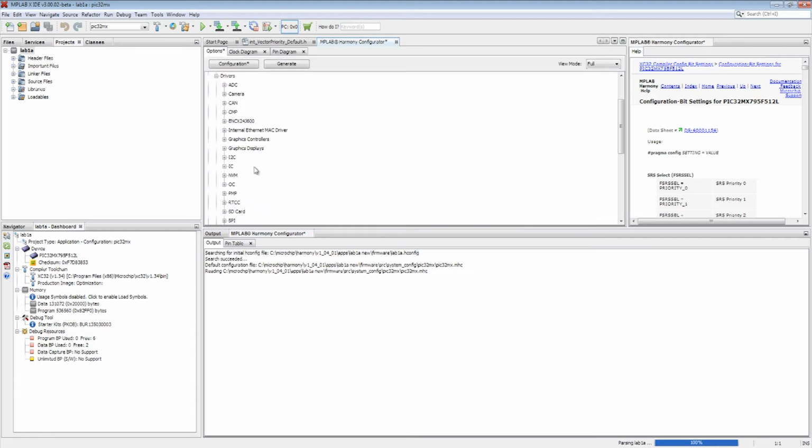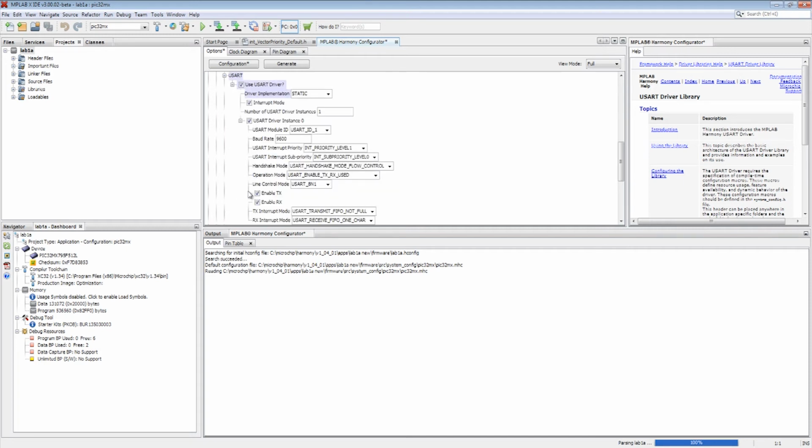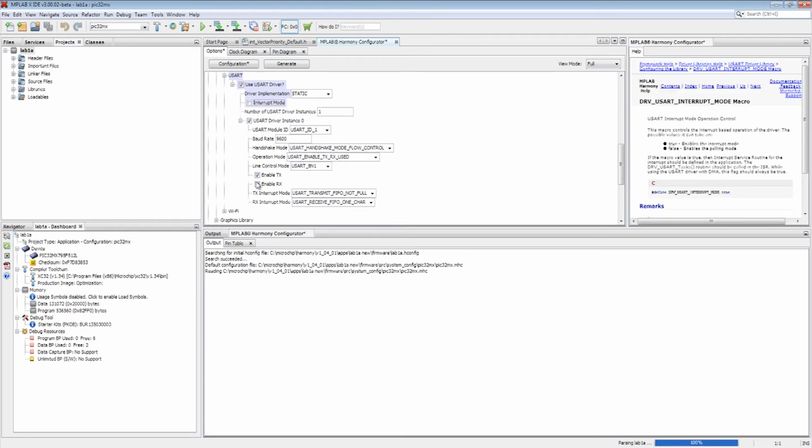The third step is to configure the drivers and the application libraries for this configuration. The drivers are in the Harmony Framework configuration option. The USART driver settings are now picked. The context-sensitive help enables the user to get detailed configuration options on the USART.